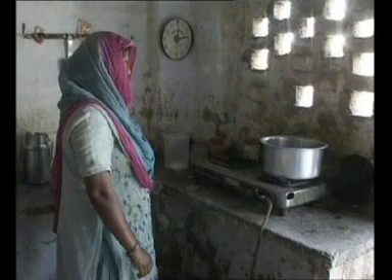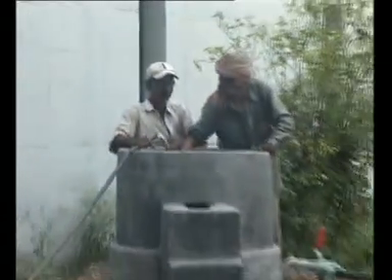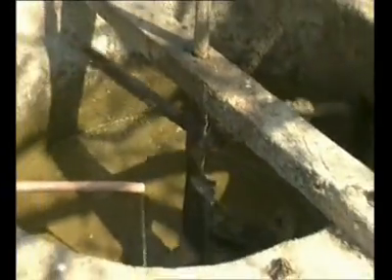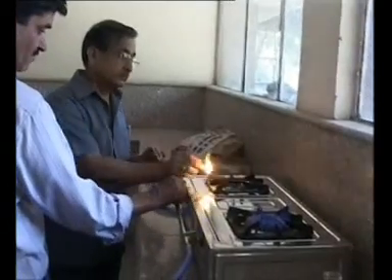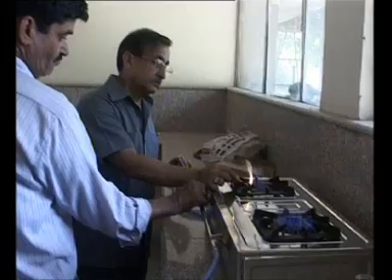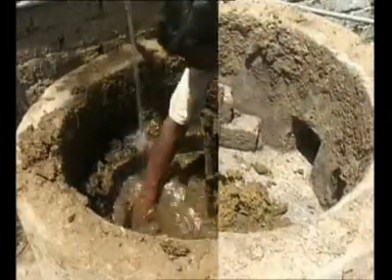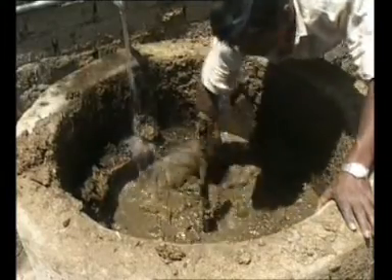After the completion of the biogas plant, we make a connection of the biogas plant to the kitchen. Now, in order to make the Deen Bandhu biogas plant operational, the digester is fed with 200 cubic feet of cow dung mixed with 200 liters of water. The biogas generation starts within 1 week's time after the initial feeding. After this, we feed the plant with cow dung and water every day to get continuous biogas supply.